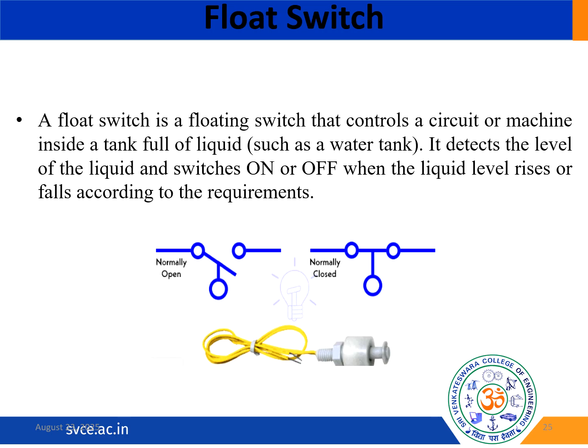Next we'll move on to the float switch. Previously we have seen the flow switch. This type we call a float switch. For example, we can see where we are going to use a float switch. When the level of water falls below the designated line, the contact arm and the rod make contact, which triggers the circuit. So the motor of the pump is activated, and the water tank again starts to fill with liquid.